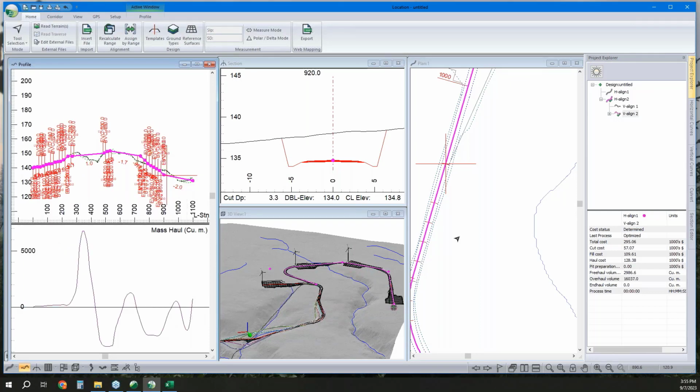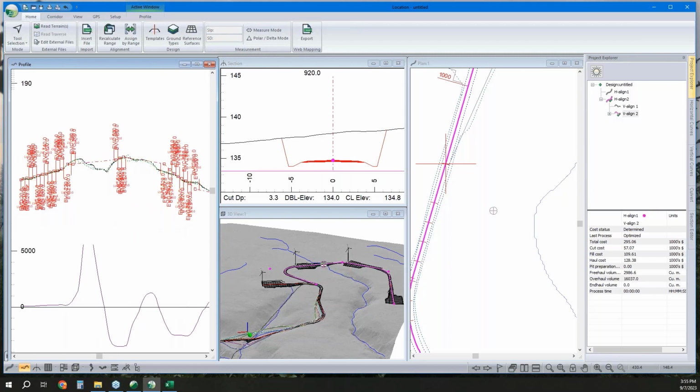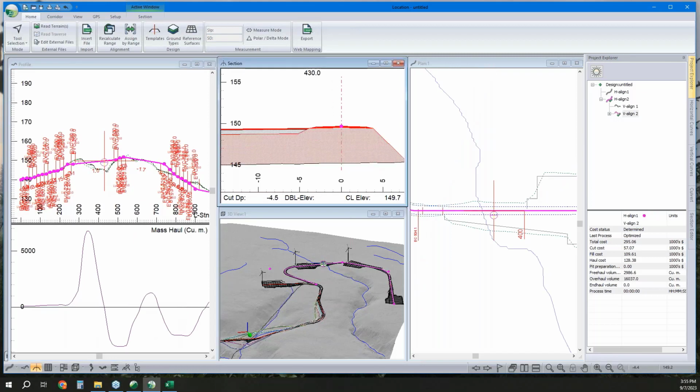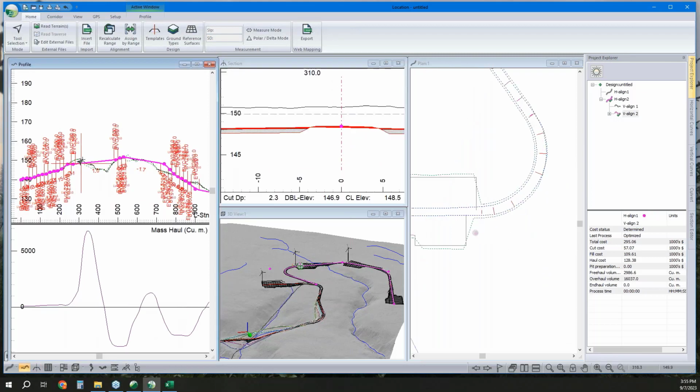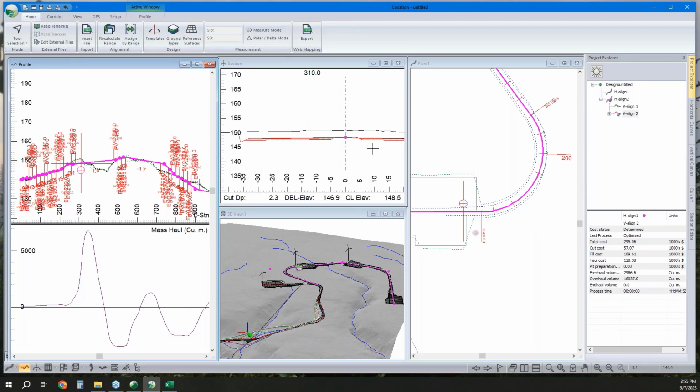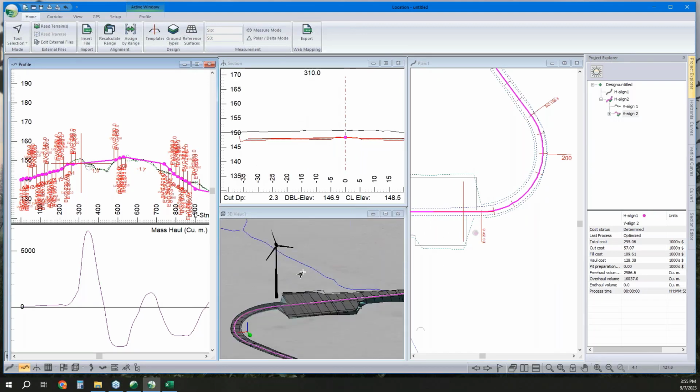Cool. And that's done running. So we can see the mass haul isn't going up to 25,000 or whatever I had, and we've shaved off about 100,000 from doing the vertical by hand. At a glance, it might look like, wow, we're really high, but we're also dealing with this massive amount of fill that we're generating right there.